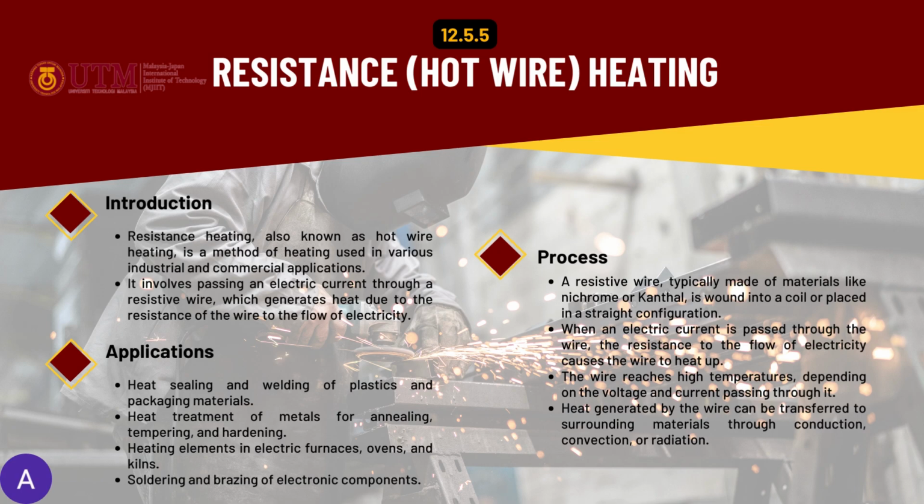a resistive wire, typically made of materials like nichrome or Kanthal, is wound into a coil or placed in a straight configuration. Then when an electric current is passed through the wire, the resistance to the flow of electricity causes the wire to heat up. And then the wire reaches a high temperature depending on the voltage and current passing through it. Then heat generated by the wire can be transferred to the surrounding materials through conduction, convection or radiation.